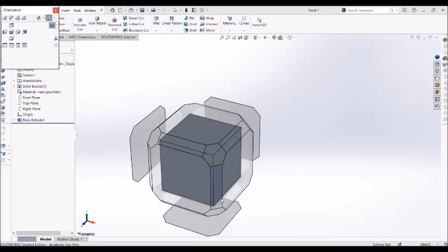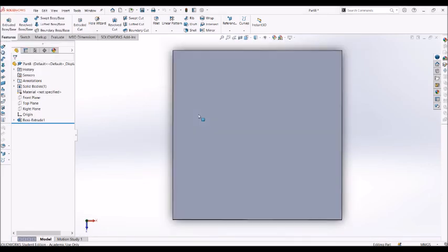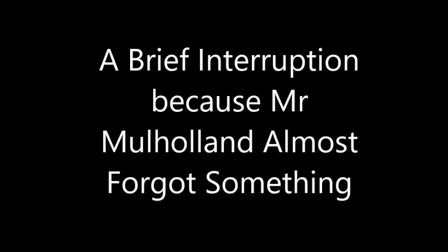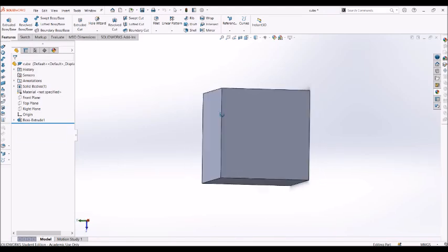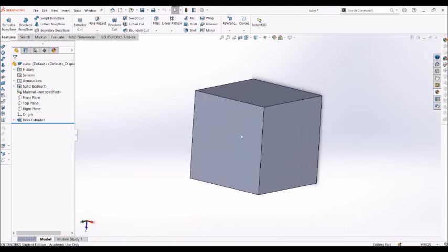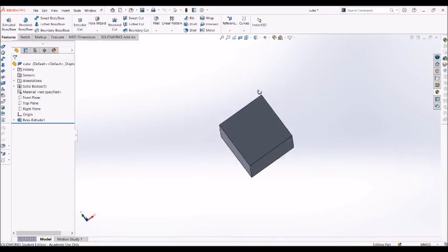So you can click the top, the sides, or you get these little angled ones. And these are basically showing different angled views. But for the time being, I'm going to click the top side. Almost forgot, another way of changing our view is if you want to look at it side on, you can click the mouse wheel and drag it, and you can customize what view you're looking at your cube in.